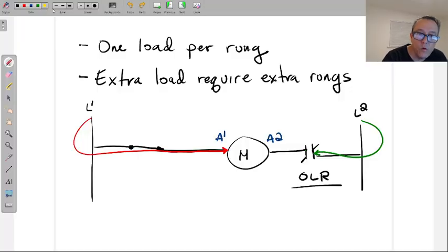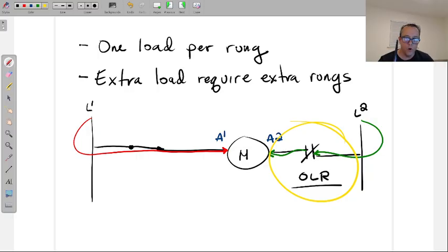And by the way, this is the only time ever in the electrical world where we will ever see this: a neutral being opened in a circuit. Or a negative, but 120, which is what you guys are working with right now in person. Online is working with DC, but same thing. Never in the electrical world do we ever open a neutral on a circuit. Neutrals are dangerous when you open them. But in a control circuit, since there's no actual amperage running through the control side of things, then there's no harm, no foul, no effect.